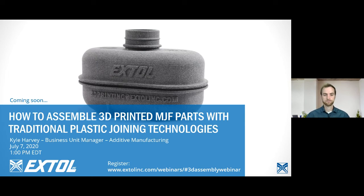All right. And then another one here, what dimensional accuracy are you able to achieve on the base design with PA12? Yeah, so the PA12, the standard that you can output is plus minus 0.2 millimeters, up to 100 millimeters, and after that it's a 0.2% tolerance.